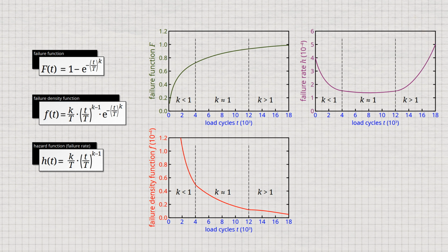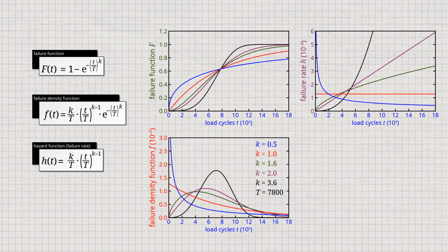Lastly, the Weibull distribution for various shape parameters is to be considered once again. What all distribution forms have in common so far is that there is a certain probability of failure immediately after the start of the service life. In some cases, however, there is a failure-free period below which failure is not to be expected. This is the case, for example, with brake discs, which first wear continuously and thus always have a certain failure-free time before they are worn out and threaten to fail.